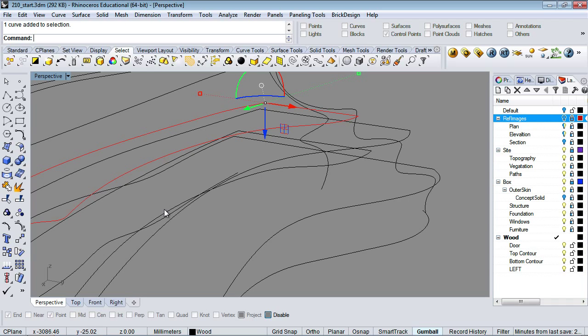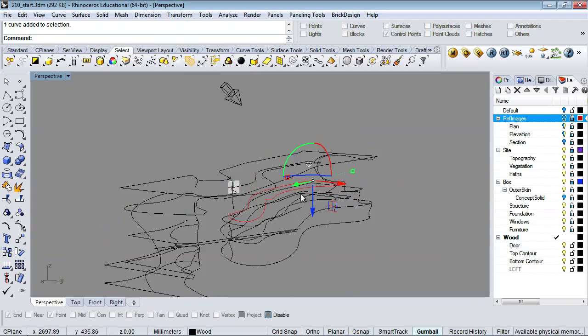Because then I'll sweep that piece and it'll go around. And then I can create this upper piece separately. And again, thinking about if I use rail, or you could use a patch on this one, for instance, and then cut out the holes where you want the rail. And then once we have this surface and this surface, we're going to use a tool called BlendSurface, which I'm going to show you next, so that it'll seamlessly blend those two surfaces together. Okay?